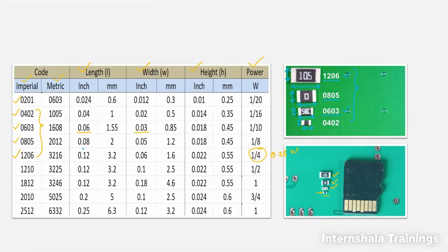So that was all about the packages of resistor, and I hope that till this point you are comfortable with the different packages. And one lesson that you should take from this is you should not use 0402 package or these components, these packages. If you are soldering the components on the PCB manually, you should actually go with 0603 package, 0805 package or 1206 package.